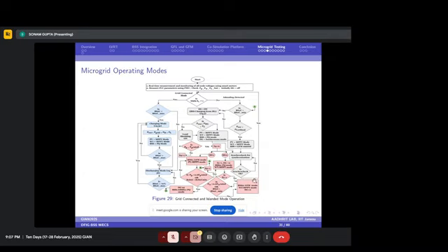Once it reaches its minimum state of charge, then in the extreme state conditions, we operate the diesel. So here we are reducing the operation time of the diesel generator, which conventionally operates instantly during islanding. But in this case, initially the battery will come into action. Once the battery is discharged and the islanding remains for a longer duration, then the diesel generator will come into action.